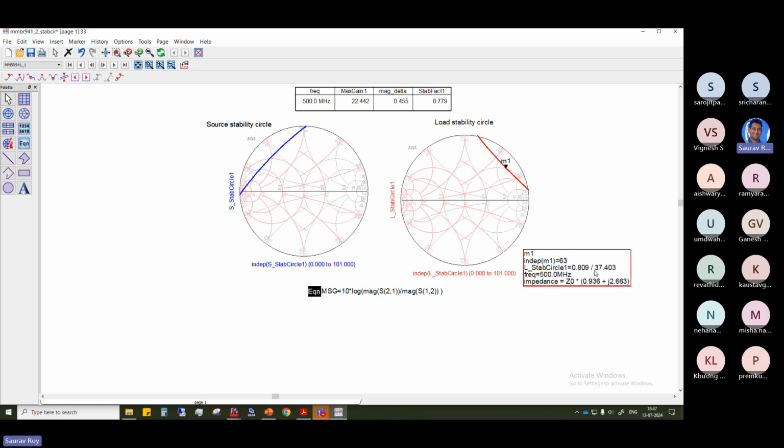It gives you the corresponding value for your impedance Smith chart, but you can also find it for admittance. As you see, this red dot is 0.5. As you go to this extreme, it will be close to 0.1 or even less. So if you take 0.1 or less, that means 50 divided by 0.1, or close to that, will be around 400 ohm, or 500 ohm. It will be less than that. So now we choose to add that.